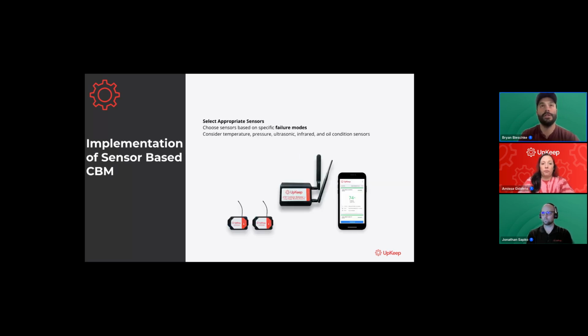All right, selecting your sensors. We want to be looking at what do we want, right? So we've identified what machines are important to us. Now, what do we want to be looking at? What do we want to monitor on these machines? We use the term failure modes here because we're making the assumption that we understand where things are failing, whether we're having bolts break or we're losing belts or we're having temperature spikes or humidity spikes or a loss of head pressure from a pump, right?